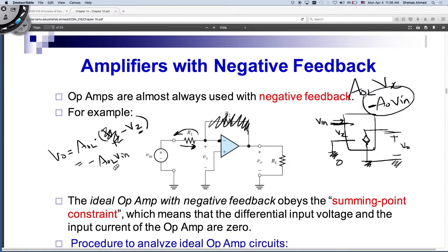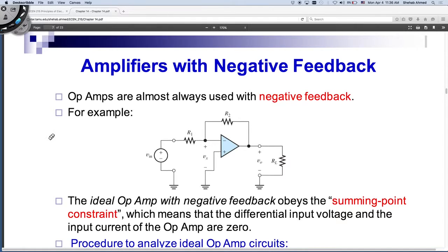It will drive my output to a very large value equal to my power supply, so I cannot see my input signal at all. I want to reduce this A, if you wish. So I've added closed loop feedback to be able to reduce or change the gain of the circuit. At the end, I still want the gain, like my filter circuits, I still want the gain.